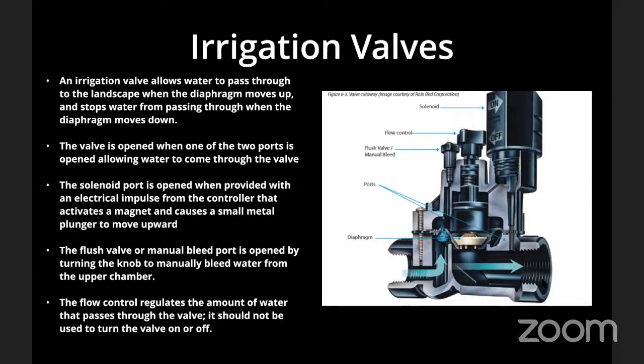And this is a pretty typical cross section of a sprinkler valve, of the valve operating part. In California and the West, a lot of our valves also have an anti-backflow feature. So the threads that screw in come from the bottom, but the operation of the valve part works the same. These things are confusing and mysterious to people. I will briefly explain it. If you don't get all of the details, that's just fine.